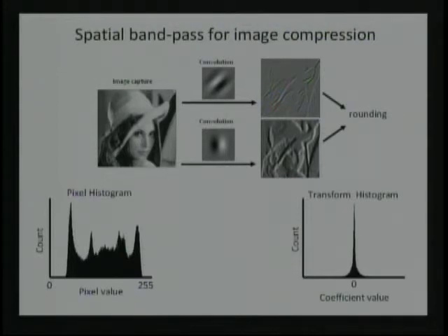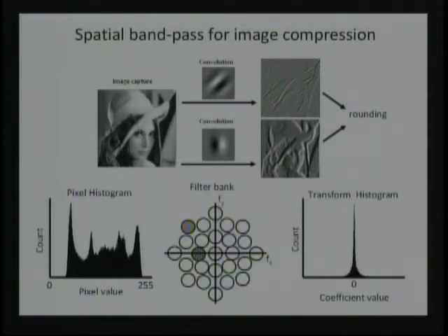And the main key to being able to build something that you can reconstruct is that you have to fill in frequency space. You have to be sure that when you look at the various bandpass filters you're using, they fill in the 2D frequency space. So for example, this one here is this band in frequency, this one here is this band here, and so on.